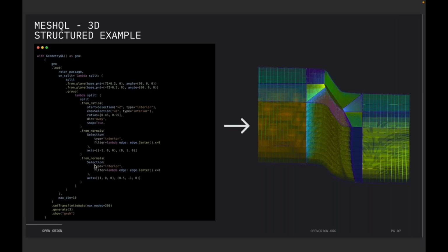So we also created a splitting preprocessor, which allowed us to pretty much do a bunch of splits very easily, so that you can establish splits with planes. So essentially we're cutting through with planes. You can actually split along the radius, the ratio along the blade. So over here, we have a 0.5 ratio for this wire here, and 0.95 over here. And now it's splitting at these specific angles. So they're splitting outwards, and you can create structured meshes very easily with this splitting preprocessor over here.